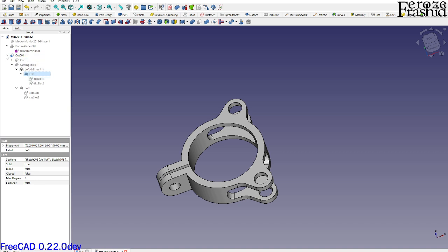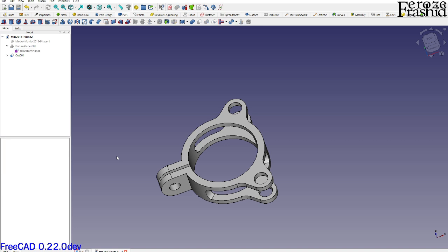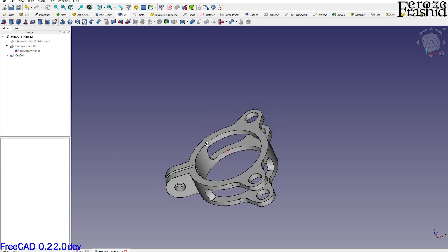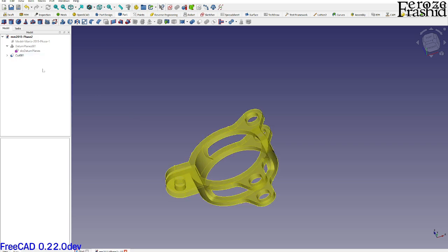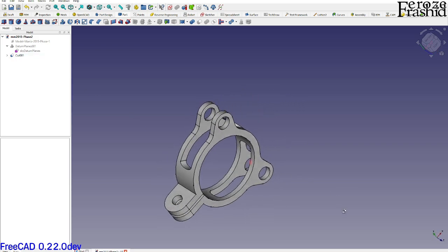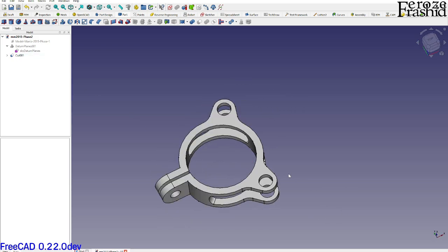Actually, we won't have to do from there. We'll have to do it from this sketch. Remember the datum plane? That's where we'll have to go in and make this 120. And that magically extends our cutting tool, makes it bigger, and eats away everything that we needed to eat away.